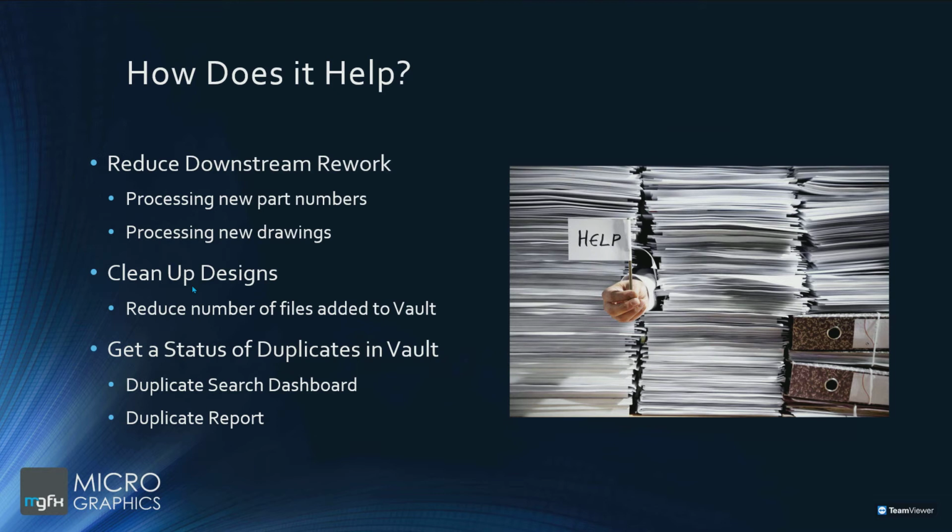One aspect that I don't have noted here for cleaning up designs is when people have reused, let's say, a Pack and Go file, and there are Content Center components within that Pack and Go. Those components can end up being checked into the project workspace in Vault rather than using the existing Content Center files within Vault.